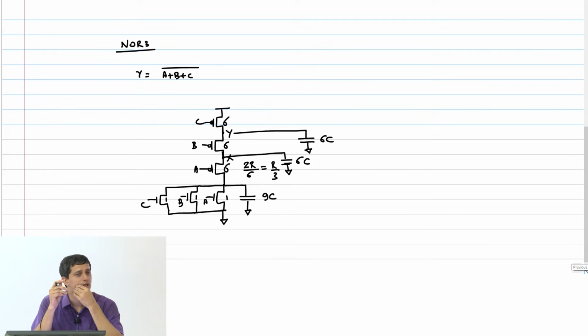So remember that this shared contacted diffusion, only in this NAND and NOR case, simple cases, it's easy to figure out without doing the layout. Otherwise you have to go into the layout to figure out what happens. Okay, so we are not worried about those things right now, in the sense that ultimately when you do a simulation with the layout extracted netlist, you will get all that information appropriately, right? But it's not easy to always say that if I give you any arbitrary circuit, how many of them will be shared uncontacted or how many of them will be shared contacted diffusions.